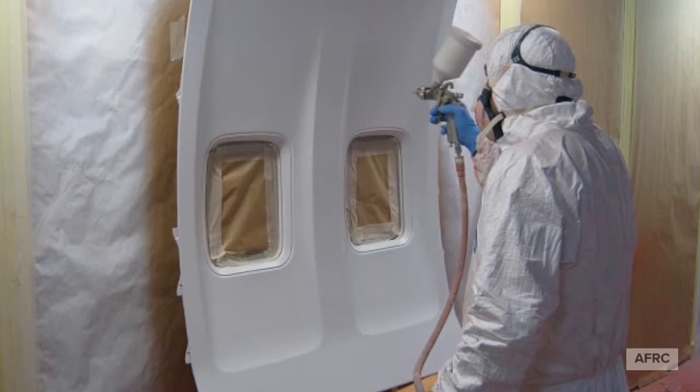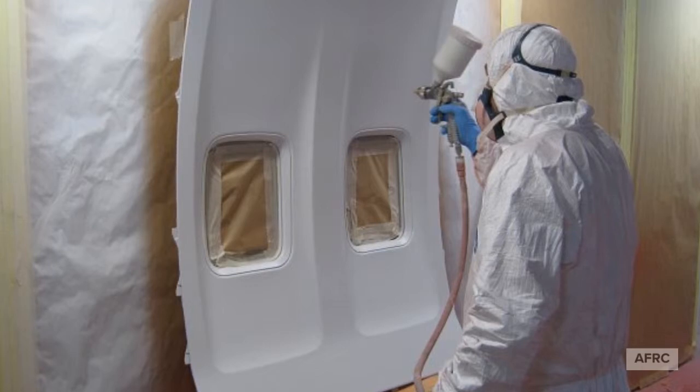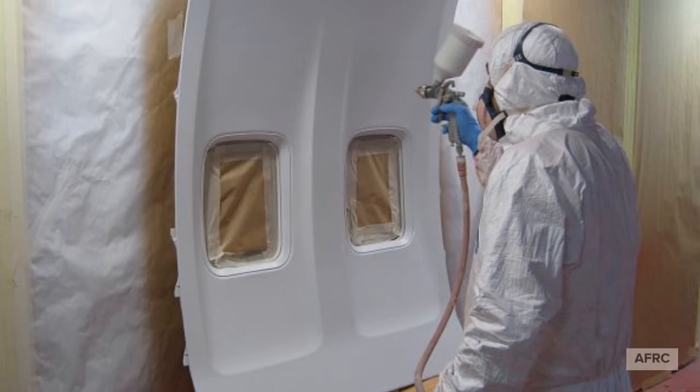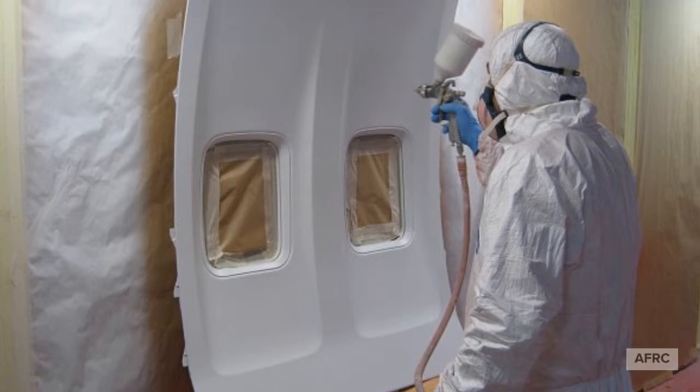And so, it's my job as an inspector, even though maybe the work order didn't specify to check that the part was clean prior to painting, I should be familiar enough with the process to know, hey, I should go in here and make sure it's clean. I should be checking the shelf life on these chemicals to make sure they're still good. It's your right as an inspector to let those techs, those mechanics, know that you want to check something out prior to moving on, even if it's not specified as an inspection.